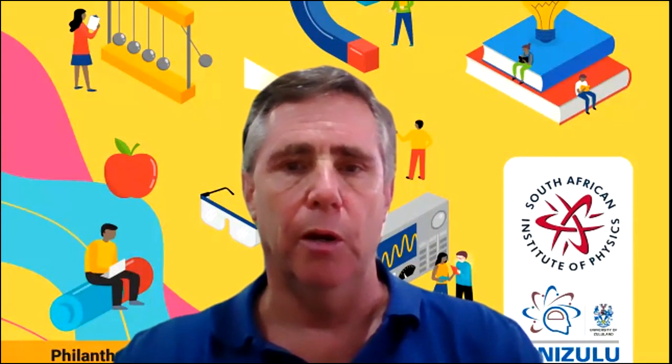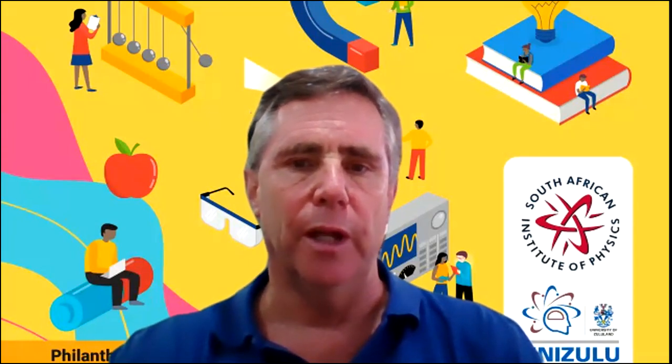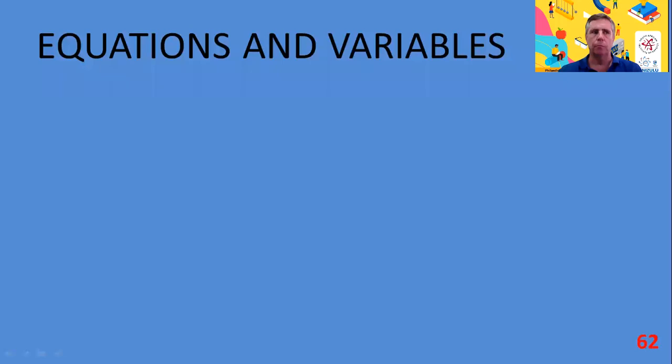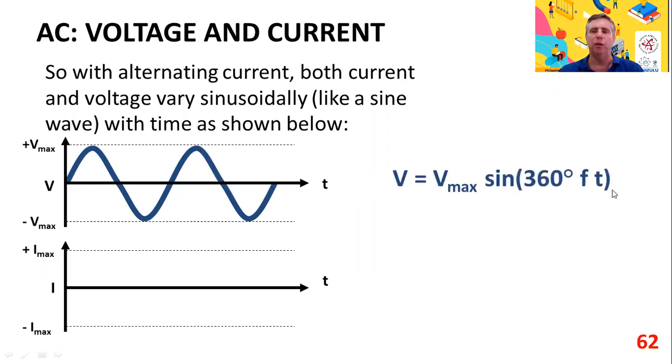So, having looked at how generators and motors work and how alternating current is produced, let's consider some of the variables and equations that govern AC circuits. You'll find these equations and variables on page 62 in your book. So we've gathered that with alternating current, both current and voltage vary sinusoidally. What it means is they go up and down like a sine wave. That's the graph, and that would be governed by an equation like this.